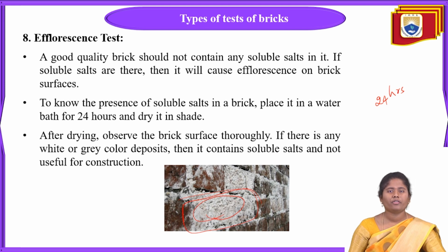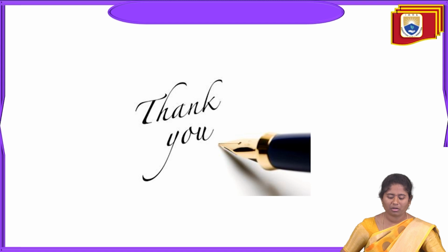After the drying process, we are going to see that brick surface very thoroughly. If any white or grey powdered deposits can be seen on the brick surface, that means it contains soluble salts and cannot be used for the construction process. This is about the efflorescence test.